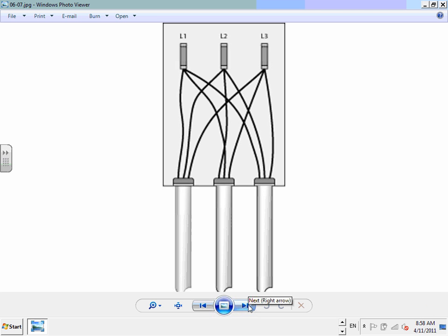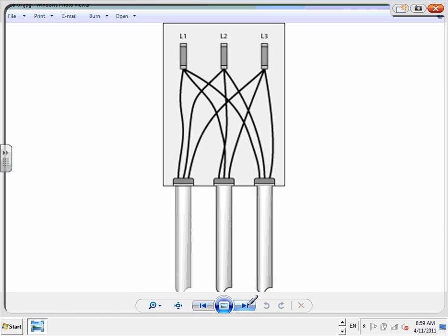Another thing is this chapter, and I'm going to go to the table in a second. Just want to go over these. Voltage drop, kcmil. The other thing, guys, is paralleling. When we parallel conductors, I want to review the parallel rules for you because you're doing it. Paralleling. Rule number one, same material.